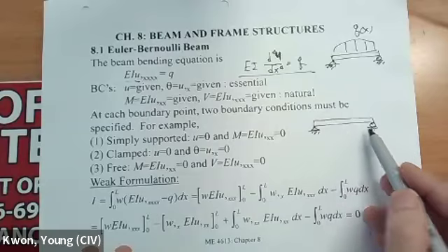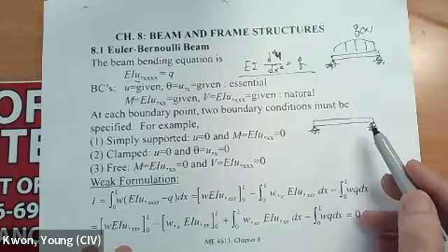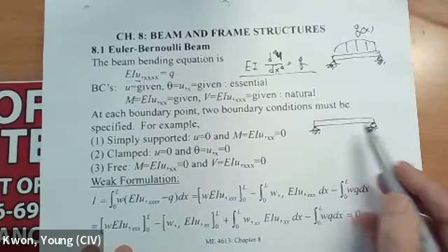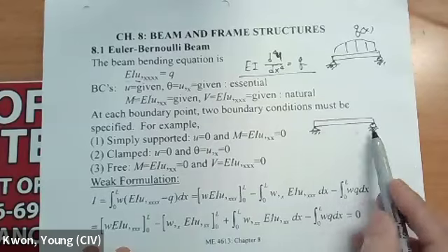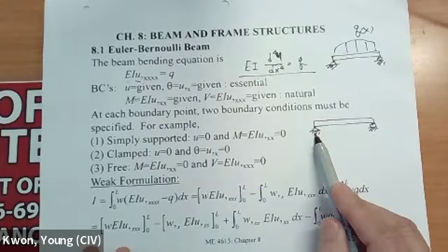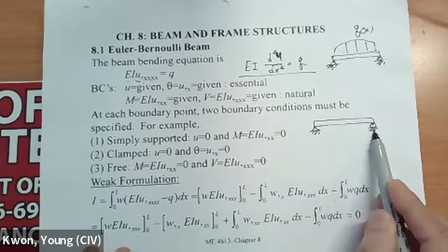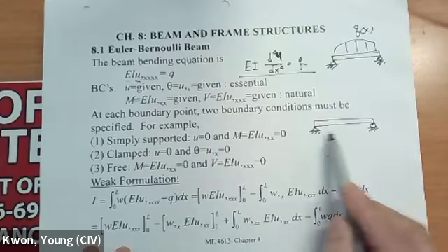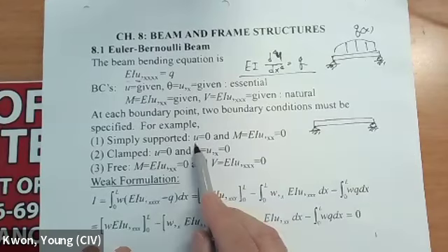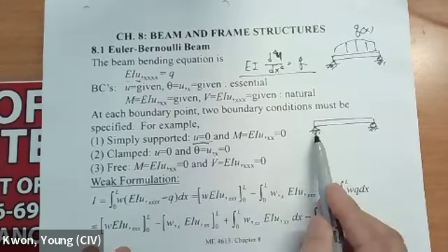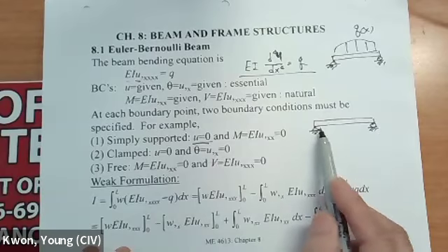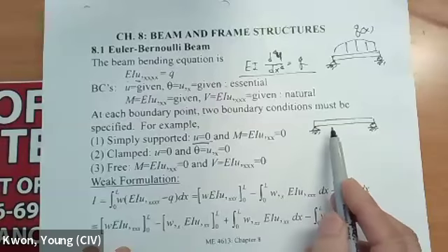If you fix both of them, then it becomes statically indeterminate. So to make it a little simplified, a simple support is going to be fixed in the xy direction, fixed in the y direction only. So in that case, anyhow, u is going to be 0, no deflection. We are talking about the vertical deflection, and we don't care about x right now because we don't have any force in the x direction, horizontal direction.